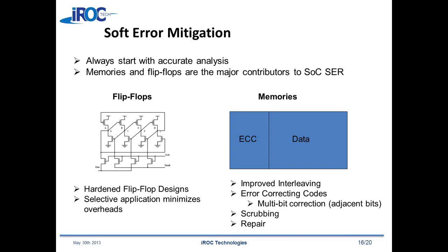And in addition, soft errors are not the only source of reliability problems in silicon. We also have bits that have permanent failures during the lifetime due to effects like NBTI. And we need to make sure that those two effects, which are lifetime effects and the soft error effects, don't interact in a way that defeats the error correction.